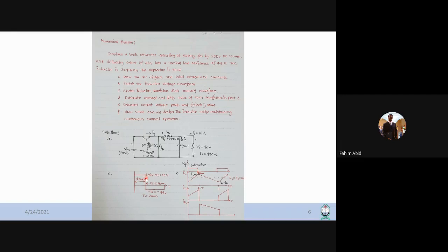If you integrate it, you can see that you have a constant value of around 152 volt, so the integration gives 152 T. So you can find the value of the slope here, as well as the slope here, and the same here. Your IL max is the same at this point, and the minimum value is the same as here.